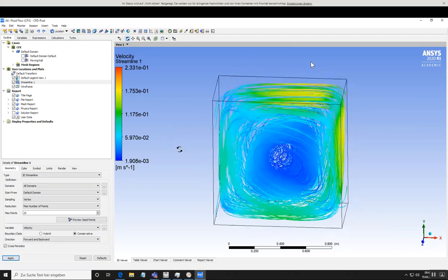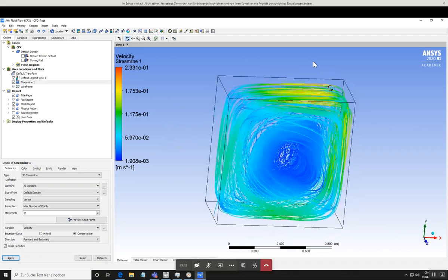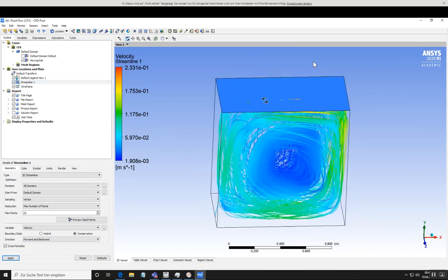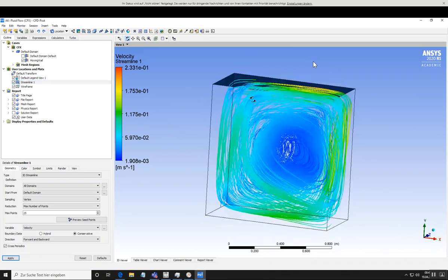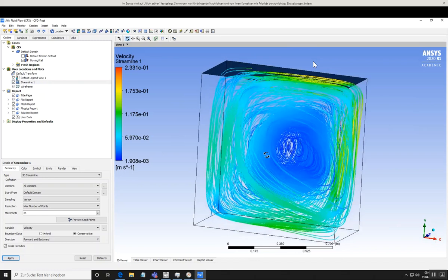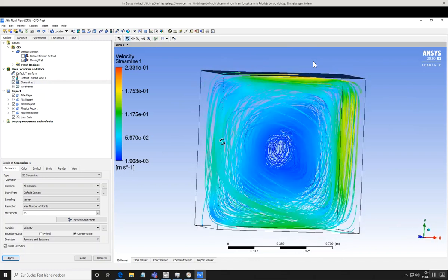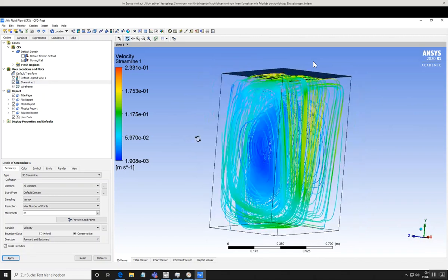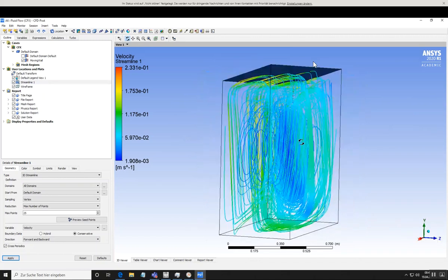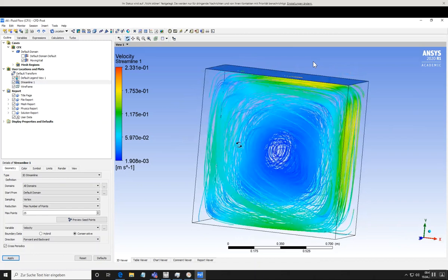That is our first swirl. We have a moving wall here at the top. Maybe I highlight it a bit. This blue region is moving. All the other things are not moving. And you can see I have a nice swirl of our water flow at 50 degrees. So I don't like the legend here too much. It's not so easy to read.